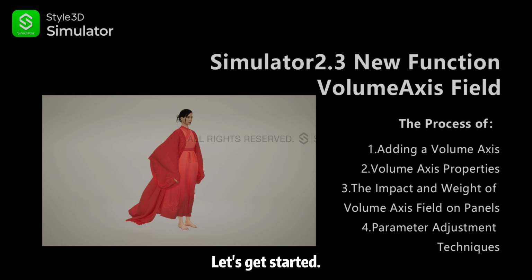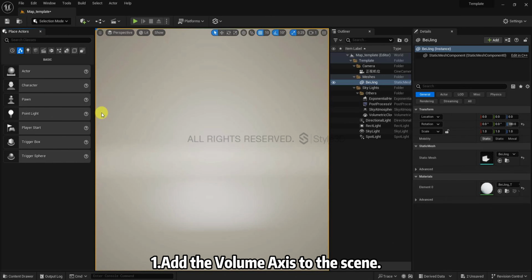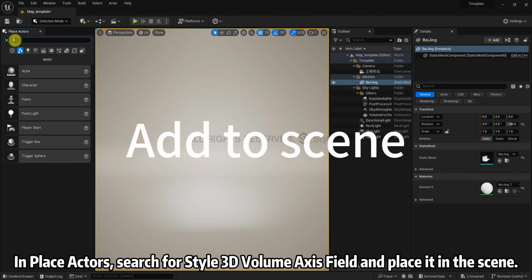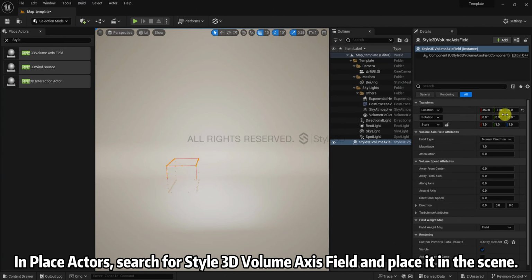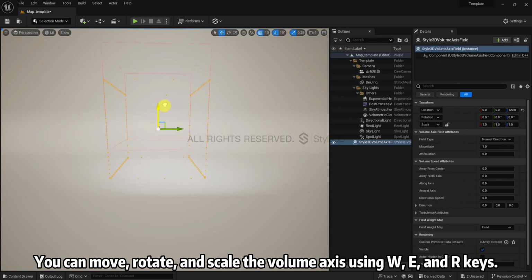Let's get started. There are 3 ways to use the volume axis field. 1. Add the volume axis to the scene. 2. Bind it to a body. 3. Bind it to a specific bone. Next, I'll explain the specific methods for adding a volume axis field. In Place Actors, search for Style 3D Volume Axis Field and place it in the scene. You can move, rotate, and scale the volume axis using W, E, and R keys.